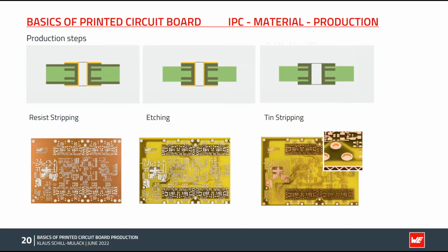Then we come to another etching process, which is called strip, etch, and strip. The result will be that the outer layers are structured. First, the resist is stripped and removed. Result is a bare copper surface, and the copper of the PCB layout protected with the tin remains.